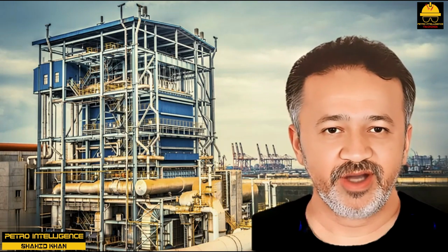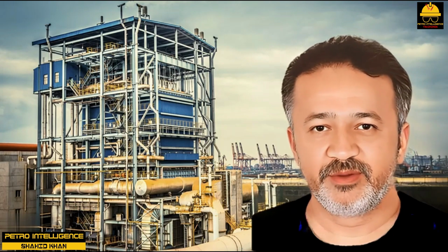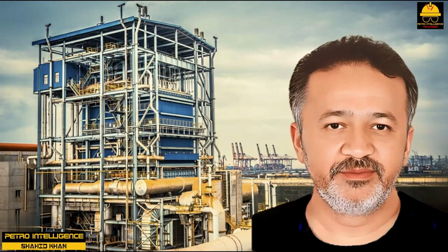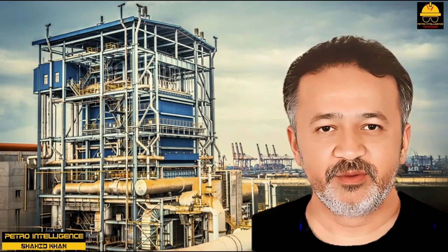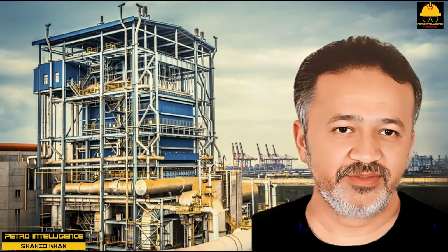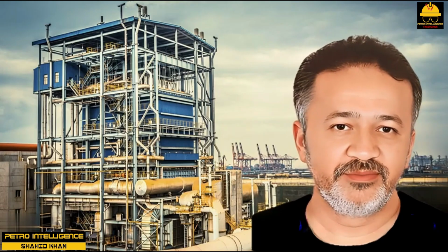In general, we are informed that this type of exchanger can be constructed of any material that can be cold formed and welded, such as carbon steel, stainless steel, high nickel alloys, or titanium. We are also informed that this type of exchanger may be used at design pressures as high as 430 psig or in vacuum service, and at temperatures as high as 750 degrees Fahrenheit or as low as -40 degrees Fahrenheit. Alfa Laval produces this type of exchanger.